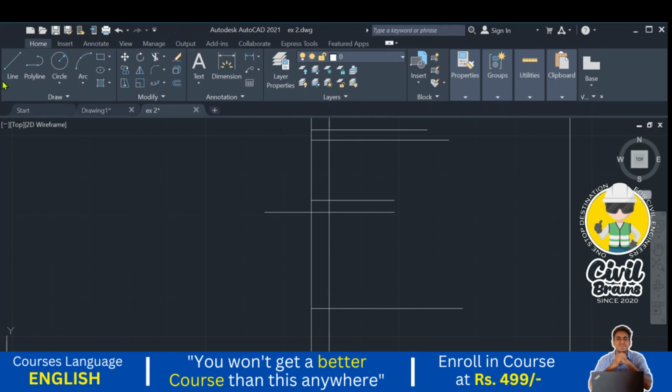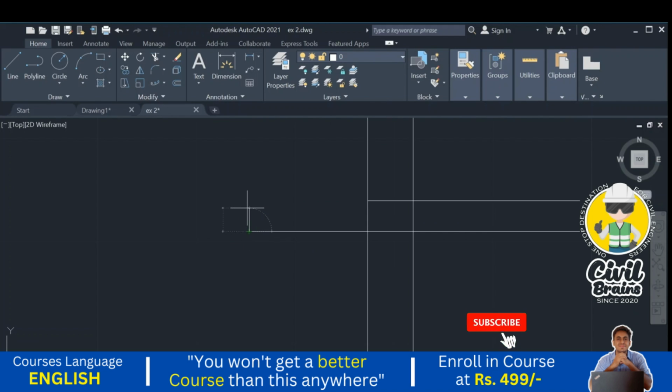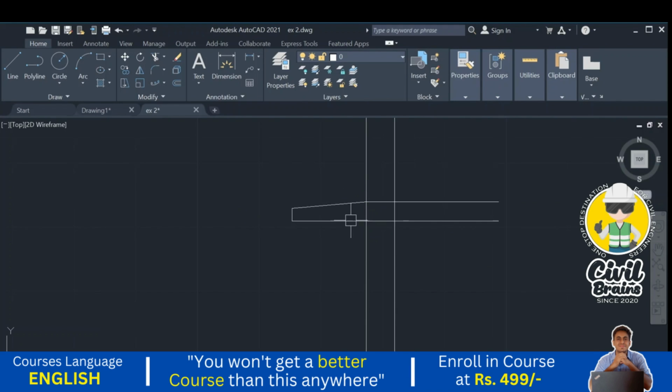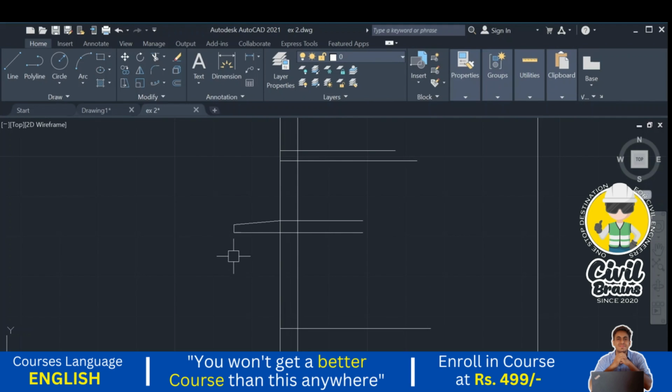Here I take a thickness at the projected end of 0.1, and at the lintel level the thickness is 0.15. I am providing a slight slope here, so whatever rainwater comes will easily drain off.